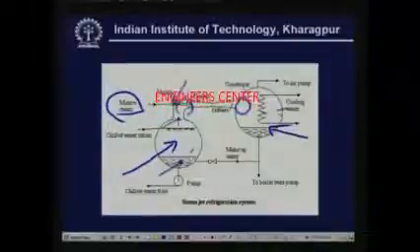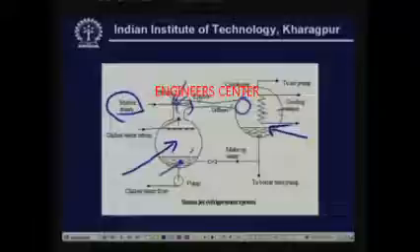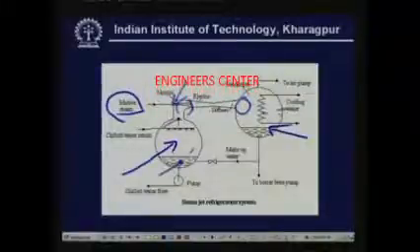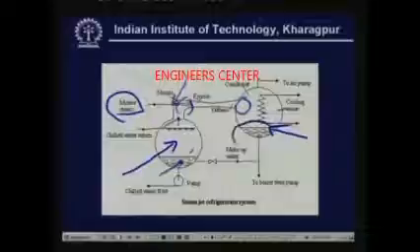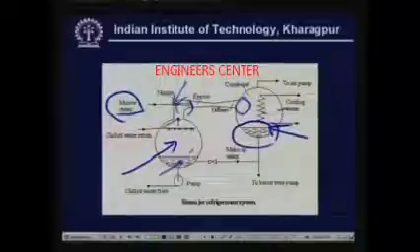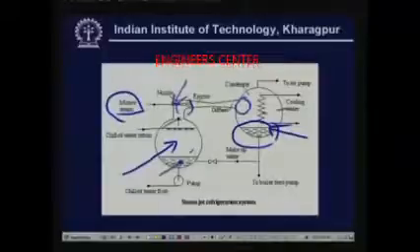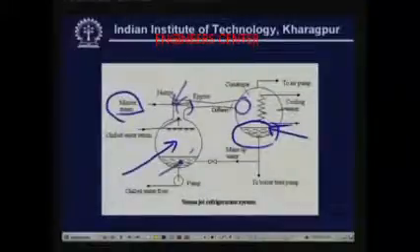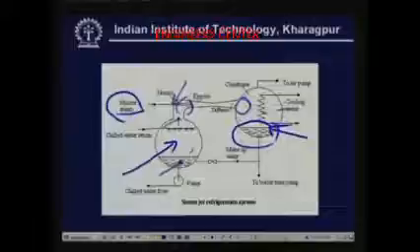When it comes in contact with the cooling water, it rejects the latent heat of condensation and it condenses. So ultimately you have condensed water here. That means you evaporate the liquid water in this evaporator drum using the motive steam and then condense the motive steam and the evaporated vapor using a diffuser, increase its pressure in the diffuser, then using cooling water you take the heat out of the vapor and condense it.